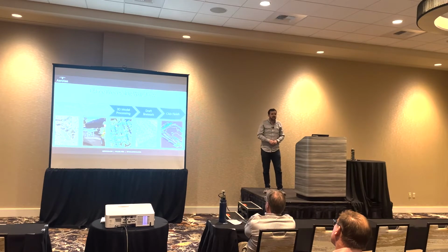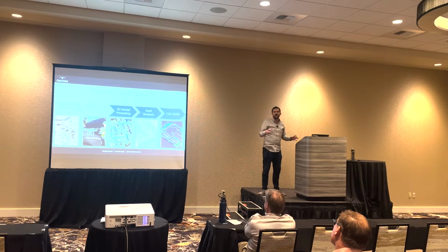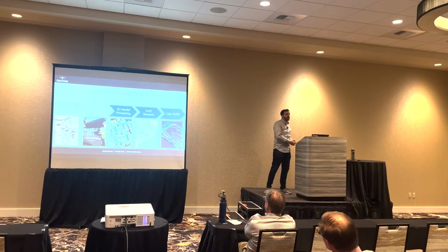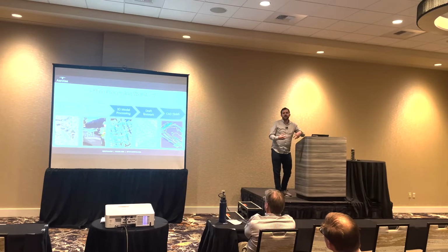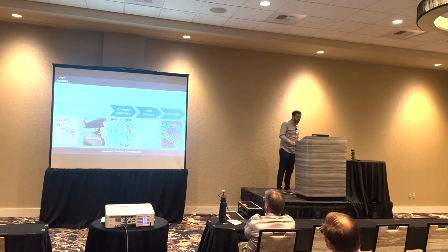3D model processing is both the photogrammetry process and the LiDAR process, which creates what we call rich deliverables: your full resolution point clouds, your full resolution ortho photos, that sort of thing. Line work is the actual vectorization of that, creating TIN surfaces, drafting your points, polylines, curved lines, gutters, etc. And CAD finishing is bringing it all together, integrating it with your boundary data, your records research, and any other data that you have that wasn't taken from the drone, which should be blended in CAD to create that final deliverable.